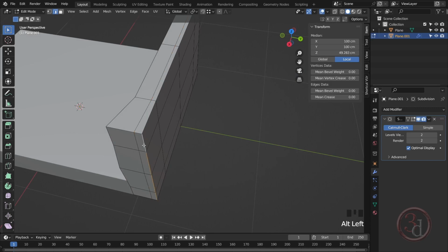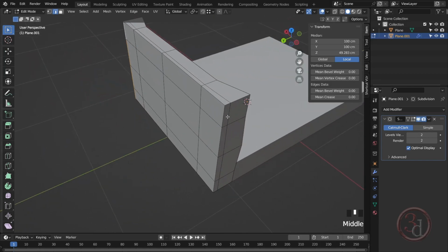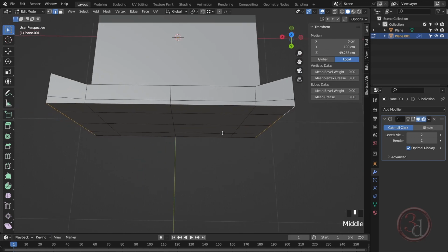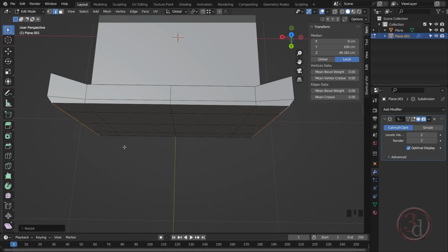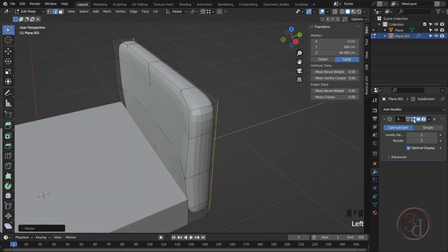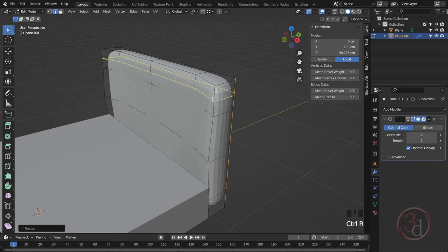Okay, and then I'll select this vertical edge loop, and I'll select this side as well. Shift, Alt click, and then I can scale it in. I will press S to scale and then press X and just bring this in slightly. Okay, let's take a look at the result that I'm getting. Okay, I'll create a loop cut over here, bring this up, hold this shape tighter.